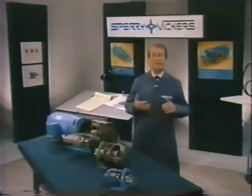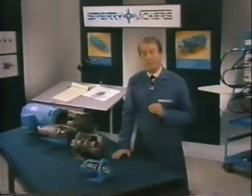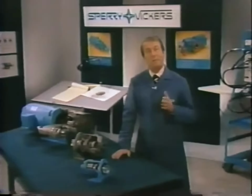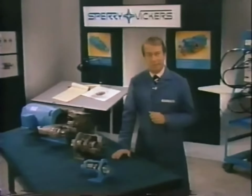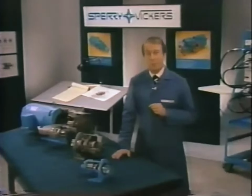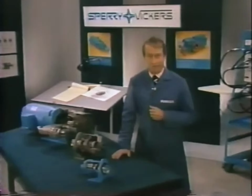Okay, that concludes our discussion of hydrostatic transmissions. In summary, these transmissions offer some important advantages. They're flexible and easy to operate. They have high horsepower in relation to package size and weight. They can be stalled without damage. The low inertia of their rotating members permits fast starting, stopping, and reversal with smoothness and precision. The output shaft speed can be varied over the full speed range in either direction with constant input shaft rotation.